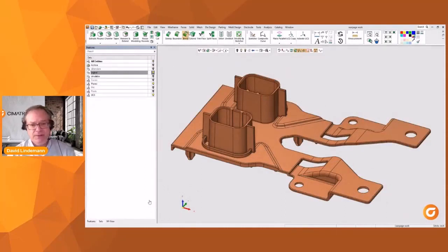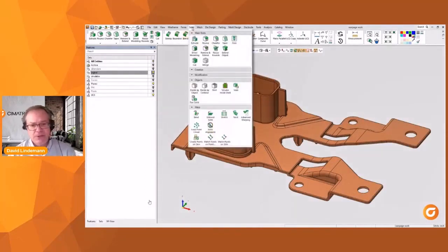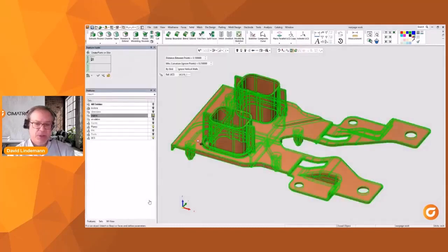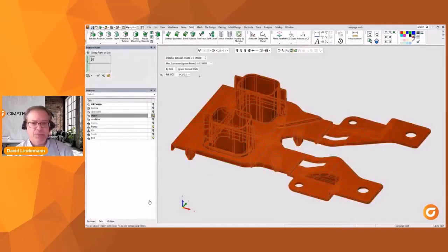Okay, so to begin the method of compensating, I'll first of all create my own point cloud. I'm going to spray the points across the CAD file, and where those points touch, that's going to be my reference. I can control the tolerance, of course, the amount of points I want to use, by how far the distance apart will be. Do I want those to go up the vertical wall? Yes, I do, because I want to capture whatever draft angle is there. So that will become a huge factor.